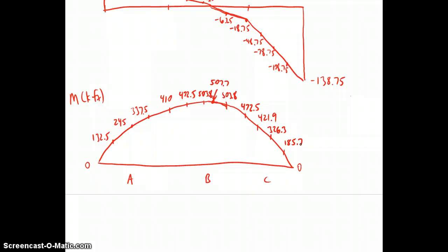error. Getting the moment diagram is a very important thing. And one other thing we want to label that helped us get to this point and get to these moment values is the fact that at 14.25 feet from the left end, shear crosses zero.